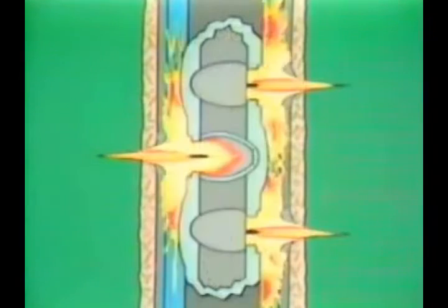Explosive pressure on the metal liner causes it to collapse inwardly along its axis, forming a high-velocity jet of fluidized metal. Moving at a velocity of 25,000 feet per second and with a pressure of 15 million pounds per square inch, the jet displaces the casing, cement, and formation, creating a perforation in only several hundred microseconds.